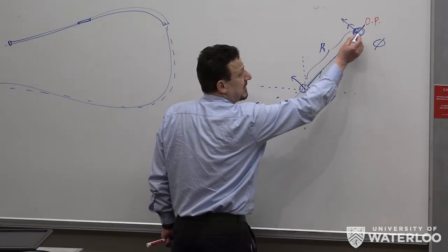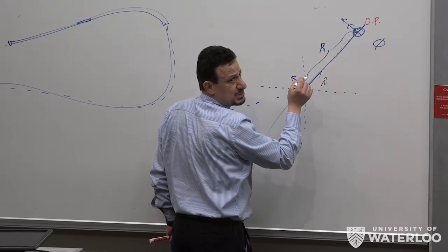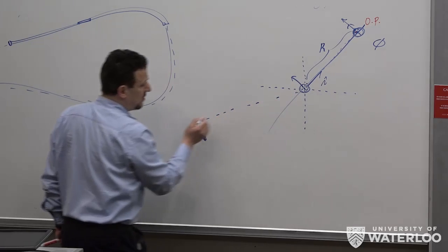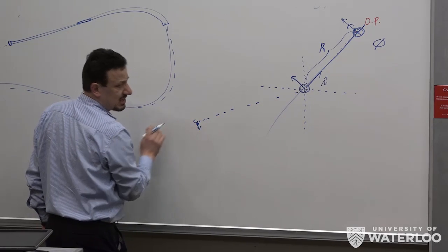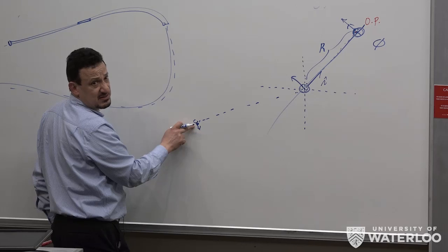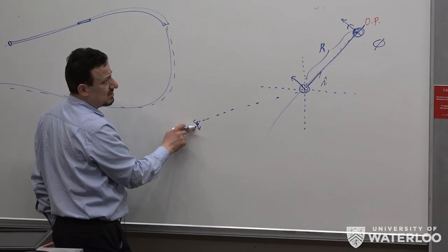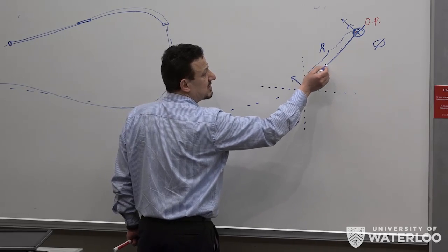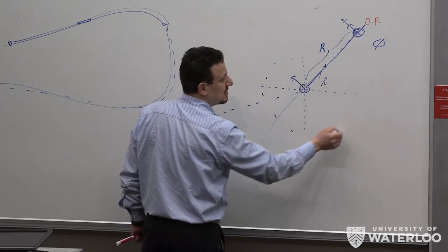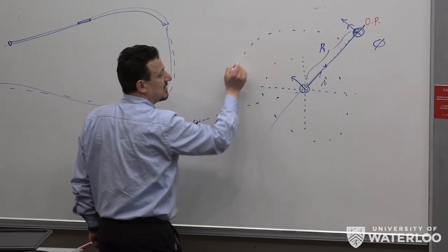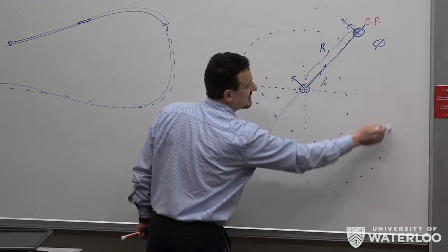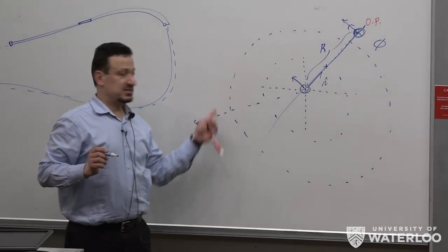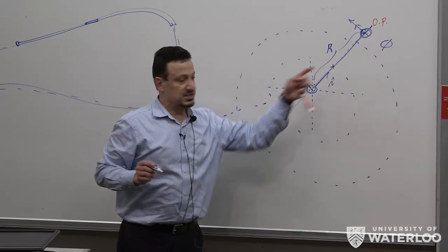The magnitude depends on, not the cross product, the magnitude depends on what? On the distance between them. So if you are farther away, the magnitude will decrease, and we can depict that as a vector with a diminishing line length. Okay? So if we keep doing this for each point in space, we find that if you are at a constant radius from the line source, you get a constant field. Where is it pointing? In the phi direction.